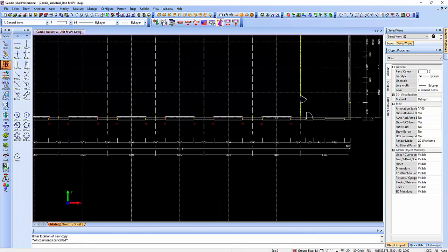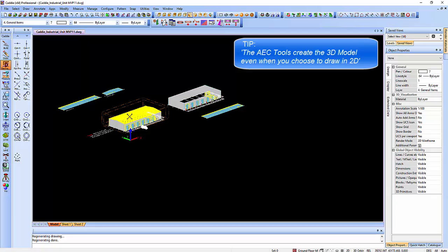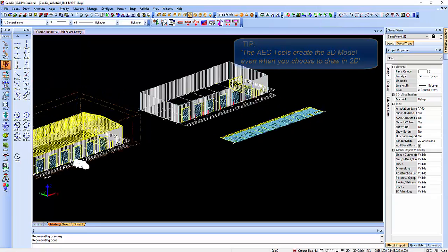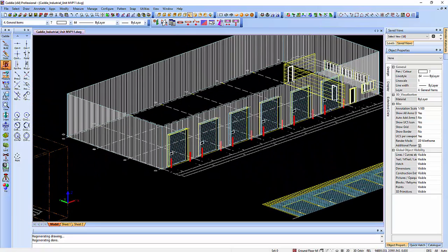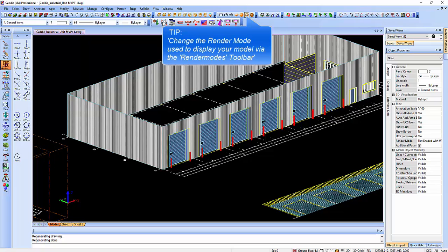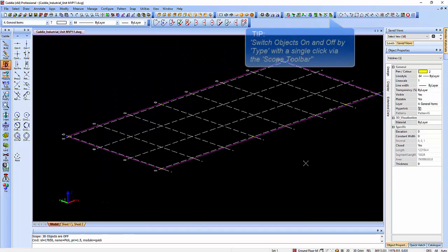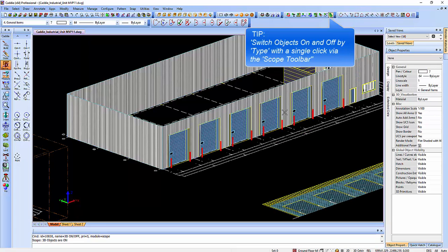Now, construction lines we're finished with, so we can remove those. If we go to a 3-dimensional view, we'll see that whilst we have the roof on the original, we haven't on here. So we'll put that in now. We'll go to a solid view. But just to remind ourselves, we started off with just a polyline there. So there is our polyline, and we can use that for setting out the roof.